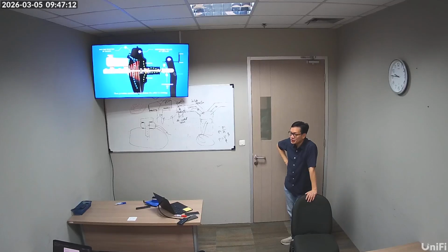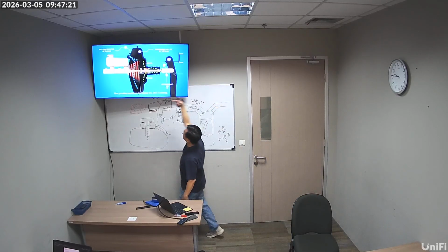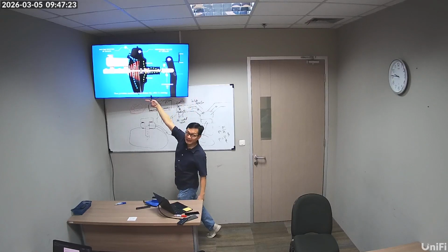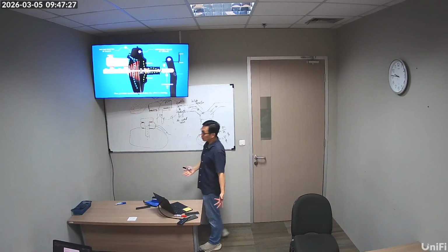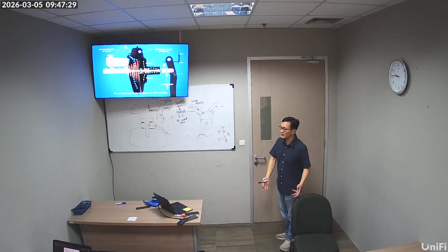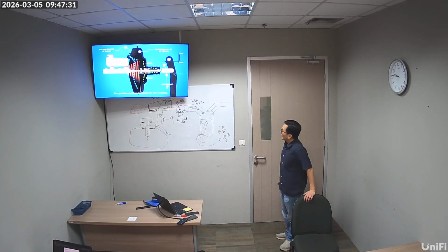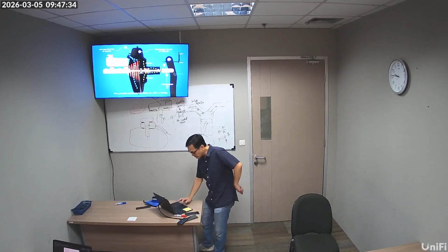Well, because the engine is off. If the engine is off, there is no vacuum, and your brake booster is not helping you. It's still working because it's mechanically connected, but the booster is not helping you at all. Your brake is actually very heavy, but the brake booster helps you.